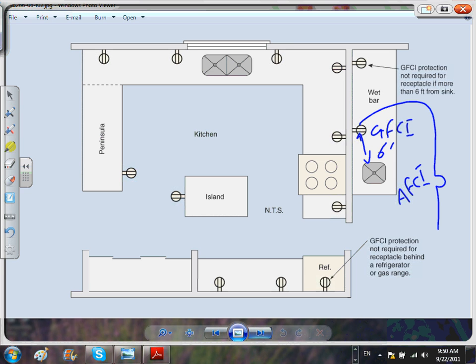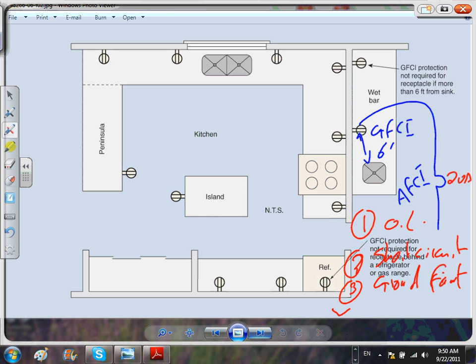This same circuit breaker can give you overload protection. Remember the overload? If this is 20 amp and you pull 30 amp out of it, what happens? It trips. Number 2, it gives you short circuit. And number 3, it gives you ground fault, the same thing as short circuit in a single phase. And it also gives you number 4, arc fault circuit interrupter. It has an electronic device in it, very smart, intelligent, that looks at the arc and trips.